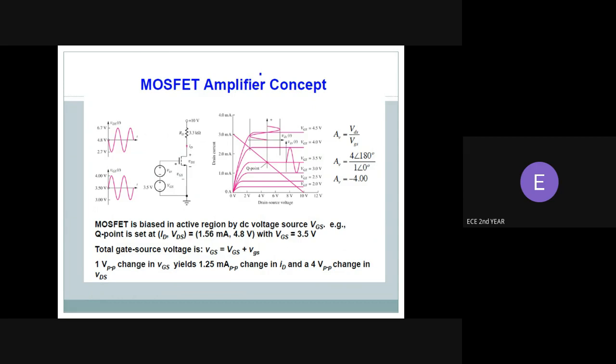The key advantage of the MOSFET is it requires almost no current to control the load current when compared to the bipolar transistor. In enhancement mode, voltage applied to the gate terminal can increase the conductivity from the normal off state. In the depletion mode, voltage applied to the gate can reduce conductivity from the normal on state. MOSFETs are also capable of high scalability with increasing miniaturization, easily scaled down to smaller dimensions.